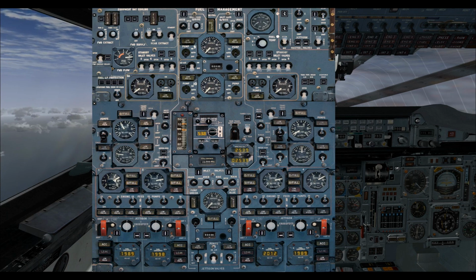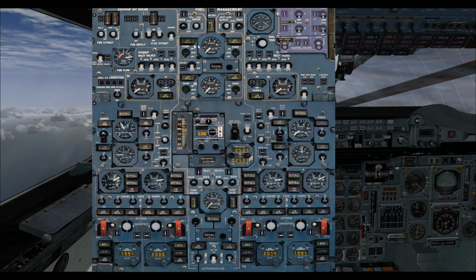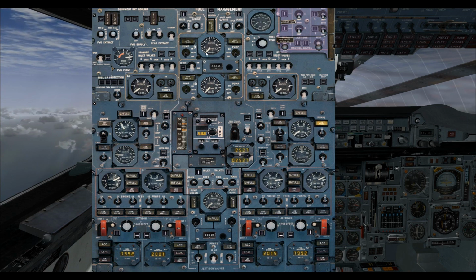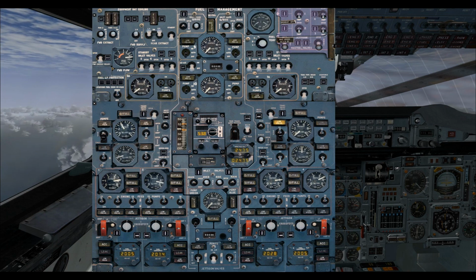And that's still not going to fix the problem. Probably what I would do after, maybe I'll do that now, stop the jettison completely, turn these off and close this back up. We're down to 28,000, so we can live with that. Then transfer fuel from 6 up into tank 9. I have to consult the chart on how to do that, but let me get that sorted out, and we'll see if that fixes things.